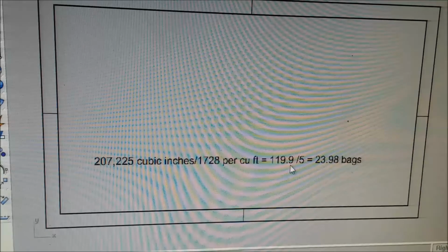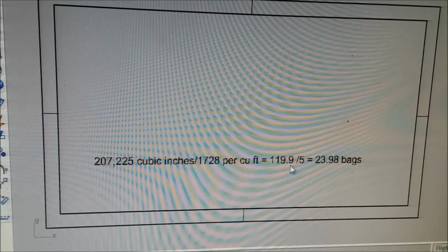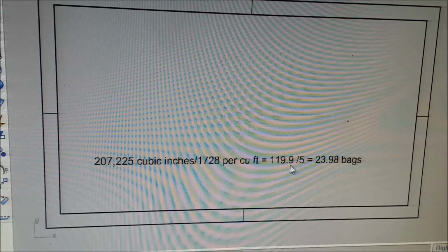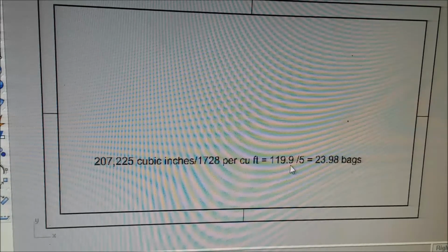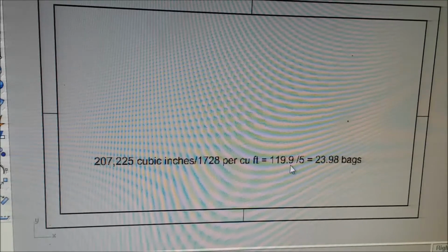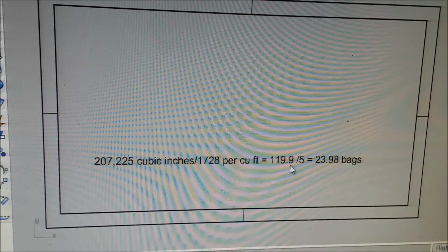So you're going to need that much cement, sand, and gravel for that 4-foot lift. And once you know what it takes for a 4-foot lift, then for the 3.5 foot, you can just multiply by 3.5, divide by 4, and that'll tell you what those are.